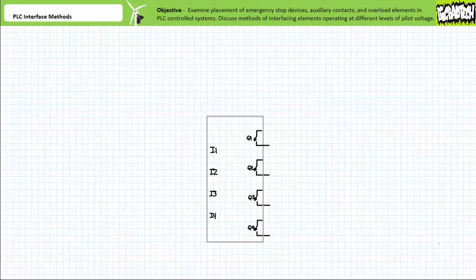When an interface element like a contactor or a solenoid operated valve is commanded to do so by a pilot signal, these interface components make or break connection to primary input. The separation and isolation of pilot and primary signals offer a degree of ease and safety for operators and technicians assigned to install, maintain, troubleshoot, upgrade, and repair electrically controlled systems.